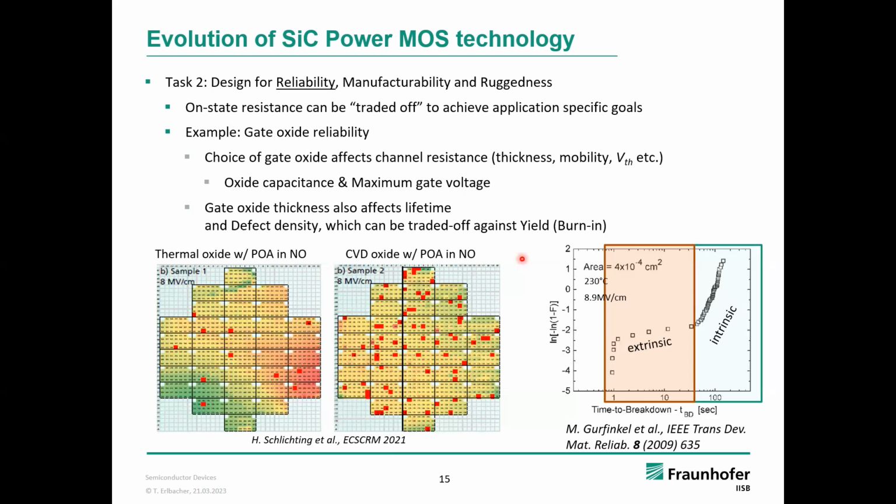constraints and applications that silicon is usually not experiencing still work well in silicon carbide, because this has not been that much investigated in silicon. And considering that the first market silicon carbide is really addressing is automotive, which usually has among the highest requirements for reliability, not going to space or aerospace applications, it is quite a challenge to ensure that you can meet something like a 1 ppm failure rate for a certain mission profile if you don't fully anticipate the mission profile yet.